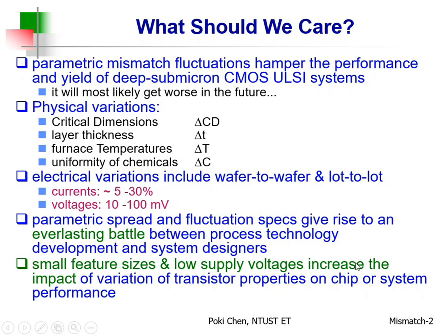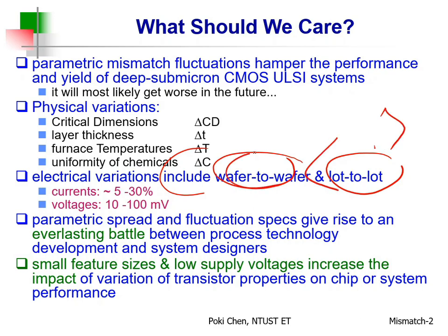According to your devices, just like your MOSFET, not only for on-wafer variations, but also for wafer to wafer and lot to lot. As I mentioned, this is the biggest. Then wafer to wafer, then die to die, then on the same die, you still need to face some kind of variations. For currents, how much in absolute value do you need to face? Around 30% at most.